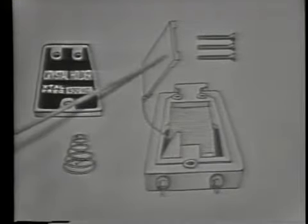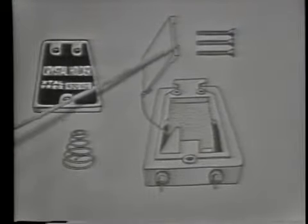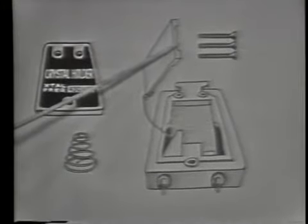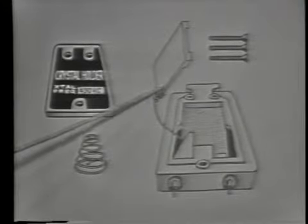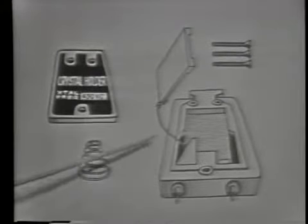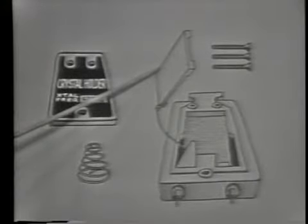The crystal will be placed in the holder between two parallel plates. The plates have an air gap between them, which allows room for the crystal to vibrate. The two plates then are connected to the pins. Now, these are the pins that will allow the voltage to be applied to the plates. And also, the pins will allow the crystal to be connected into a circuit in much the same manner as a vacuum tube. The spring will keep a constant pressure on the plates and hold them firmly in place.